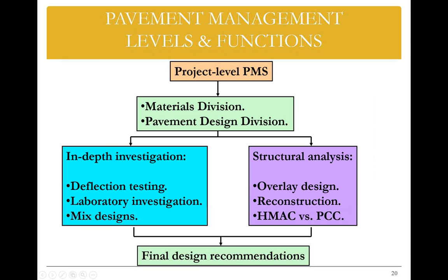And remember why it's in-depth investigation: because it's a project level. Project level concentrates on one single section, and now we really need to look into very detailed information regarding deflection testing. If I put a certain load on the road, I'm going to have strain gauges to measure how much deflection I have, to understand the stiffness of the road. Also, I need to do laboratory investigation.